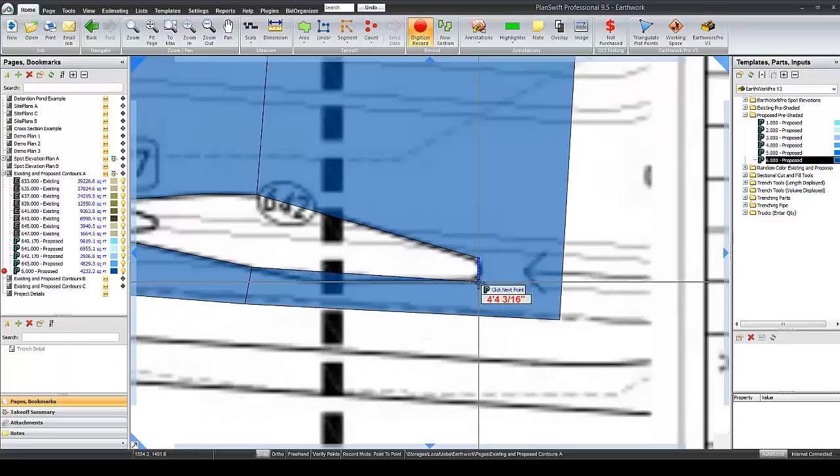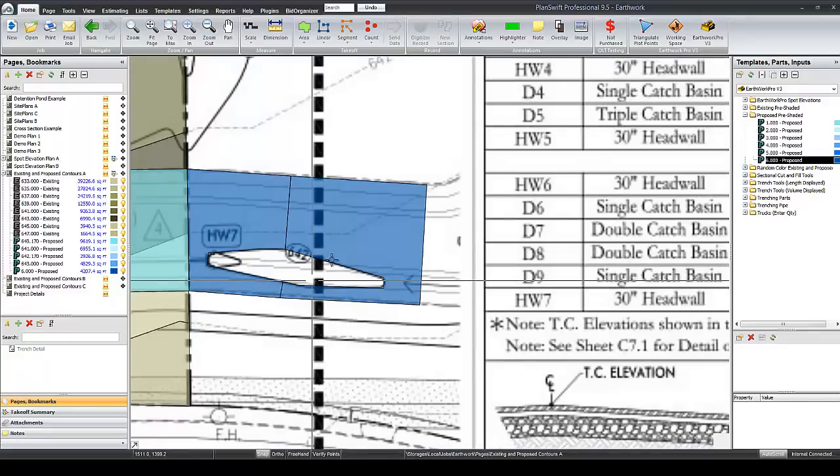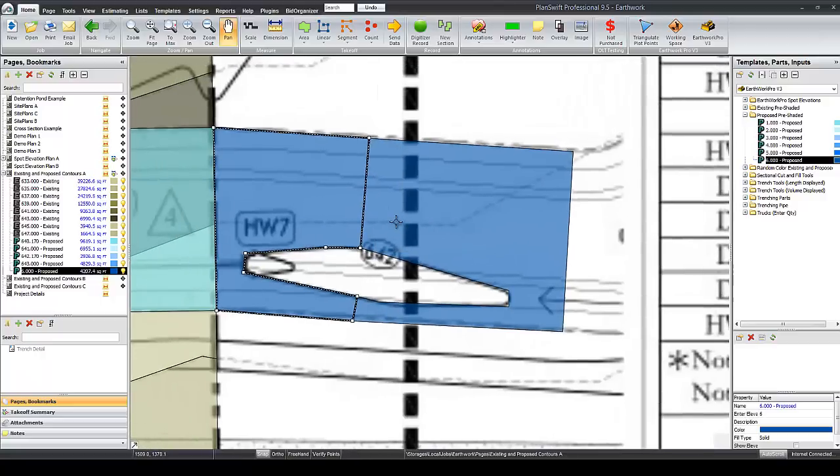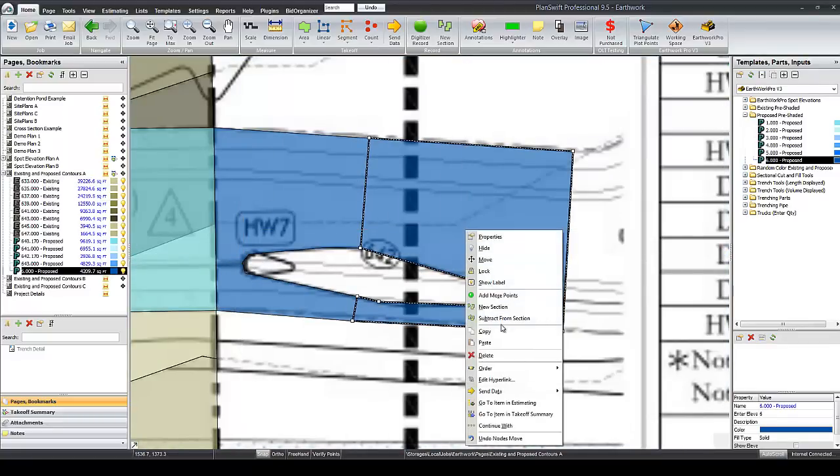I'm not doing a perfect diamond here, as you can see, but essentially there's no subtracted section. I have two shapes here that basically cup around this area that is fully enclosed now by my digitized sections. So if you're going to have to subtract something, you can't use the subtract from section function here.